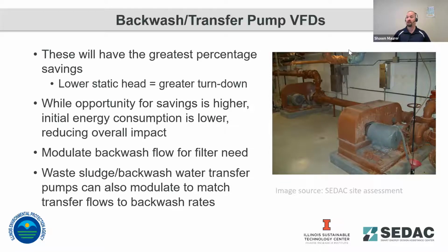Understanding how affinity laws work for pumps, which is talking about pumping energy: for each percent reduction in speed, if you cube that, that's the reduction in power you see for a pump. But if you square that, that's the reduction in head pressure that you see. And so for pumps in a high head pressure situation, since you're reducing the speed of the pump, you're also reducing its output head pressure. That puts a limitation on how slow that pump can operate, and that limits the energy savings potential. So it's very important to understand that, and it can help you analyze that in a report.